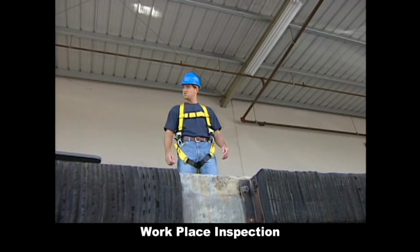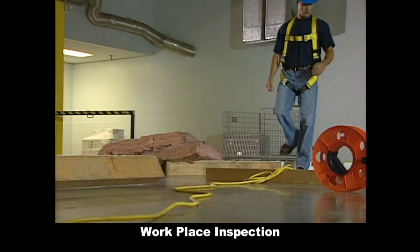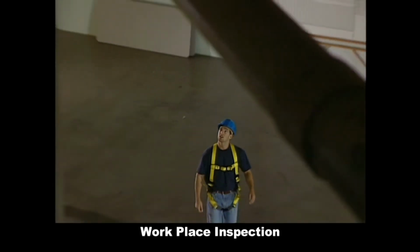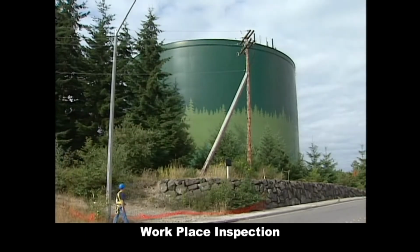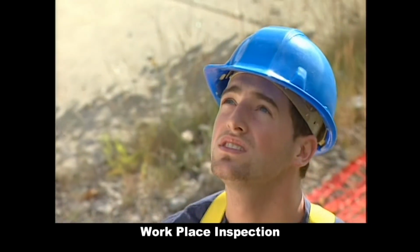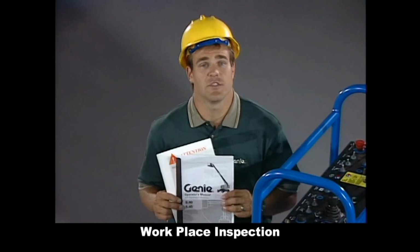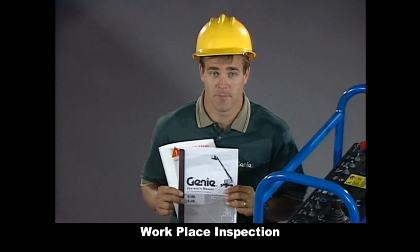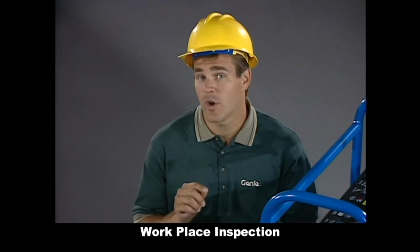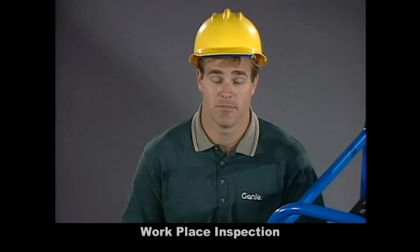Keep your eyes open for drop-offs and holes, floor obstructions, and hazardous locations, overhead obstructions, electrical conductors, wind and unsafe weather conditions. The complete inspection is listed in the Operators and Responsibilities manuals. It is also important to note that you, as an operator, have an obligation to inform the user or owner if a work environment contains even one thing that will prevent you from safely doing your job.